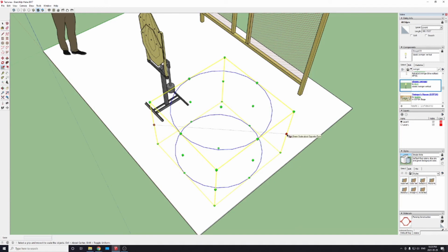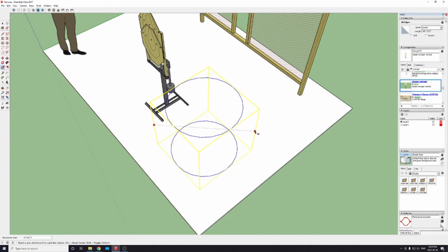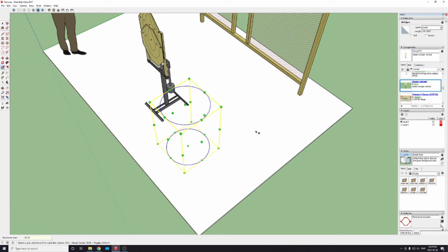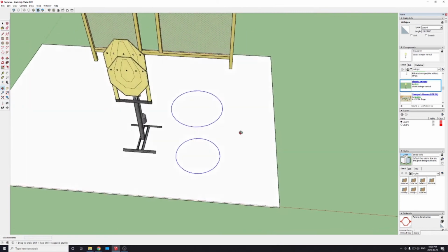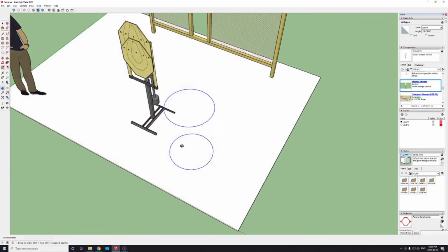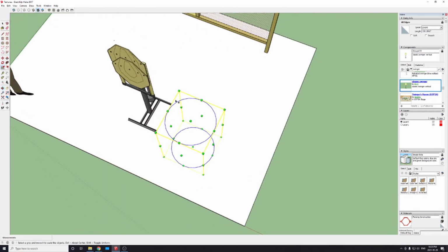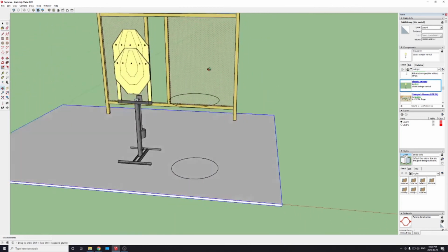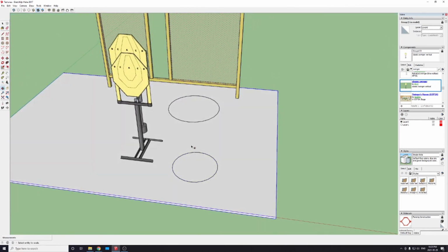And if this is 24 inches, if I was to scale this down 50%, so 0.50 comma 0.50, now this should in theory be 12 inches by 12 inches, like a perfect circle as opposed to an oval. Okay, so now I've ended up with a top and a bottom of a barrel. So I'm going to select this again, hit M for move. I'm going to move this up again, but now I only want this to come up 18 inches, half of 36.